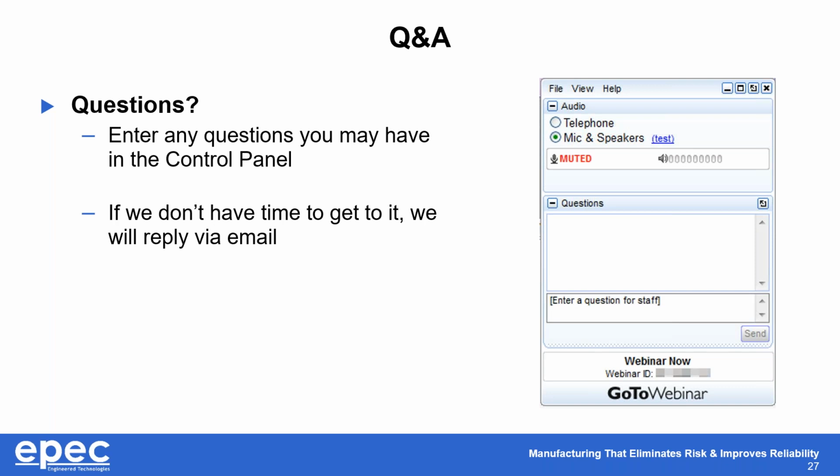But with things like laser direct imaging now, if it's only a 4-panel job and you're adding 4 more layers, that's just 4 more images. And when it's coming right out of the LDI, it's really not adding a ton more time. It's really minuscule. You may add a little bit more time at the electrical test side because you're adding some more nets, but technically going from a 12 to 16 layer really isn't adding a whole lot more time from our perspective.